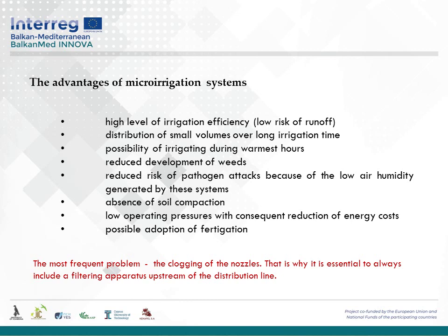And to the end, with the micro irrigation systems, we can also apply fertilizers and pesticides or other additives to the plants with practically no cost of delivery, and this also offers the opportunity to split the doses of the fertilizers into really small, daily amounts, and this is something which contributes to significantly increase the efficiency of the fertilizers, the efficiency of the nutrient supply to the crop, to the plant.